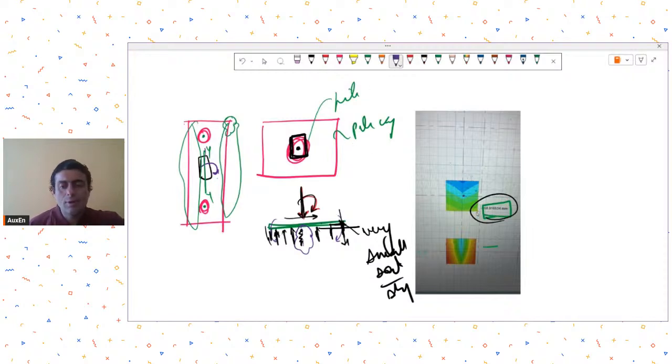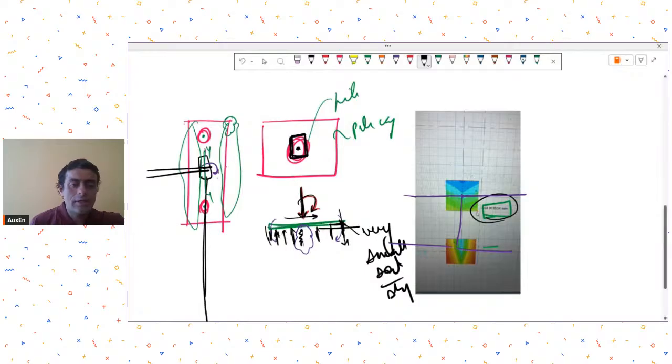Now generally what you can do is tie it up with some tie beams. Generally, single pile caps and double pile caps are usually tied with some tie beams at the plinth level or at the ground level. Okay, number one. Number two is that you can assign the soil supports. Again, as I just said, even after soil supports, you may still get some large deflection values because the soil spring stiffness assigned is pretty low.